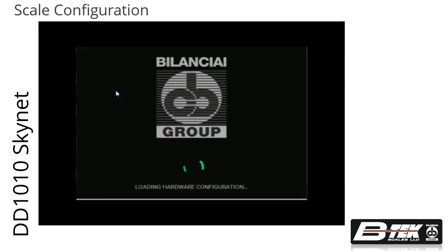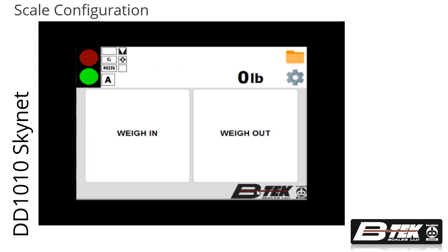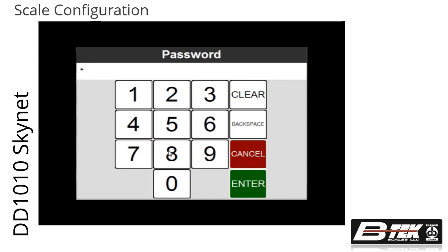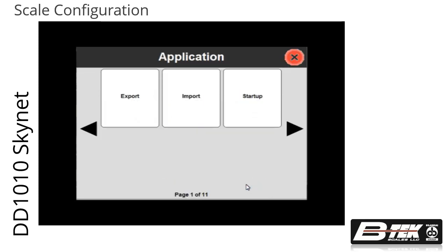The initial screen displaying touch within 5 seconds to configure is used to test hardware, calibrate the touchscreen display, and change the operating system language. Press and hold the B-TEK button until the logo turns red. Then enter the technician's password 2835. If the password's been changed, contact B-TEK's technical support to reset the password.